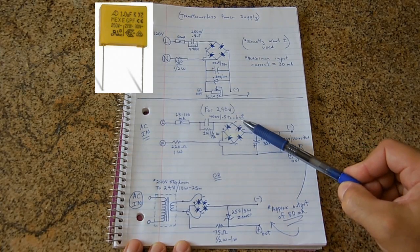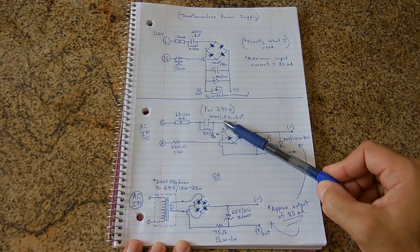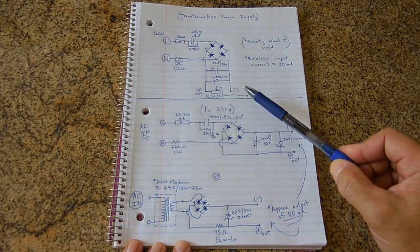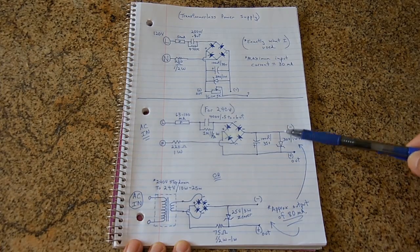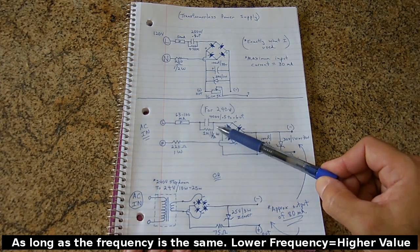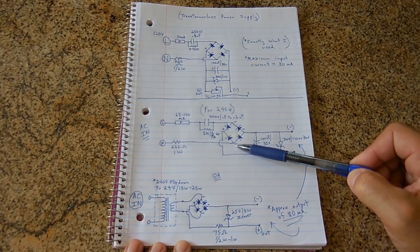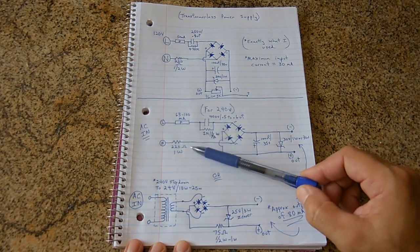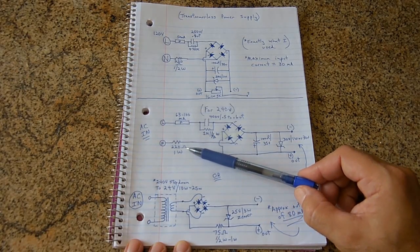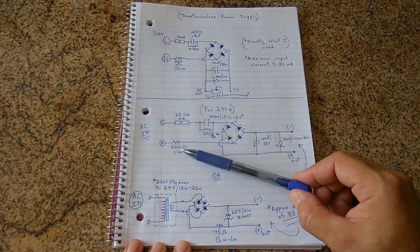0.5 to 0.6 microfarads. Now because we're using higher voltage, it requires half the capacitance to produce the same amount of current at the output. Use a 1 meg ohm resistor, 1/2 watt, in parallel with the capacitor, and then the other alternating input right here connects to a 220 ohm resistor, 1 watt, and that's also to limit the inrush current.